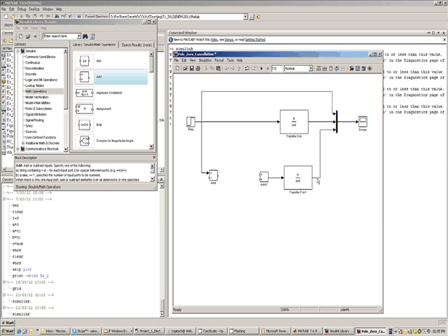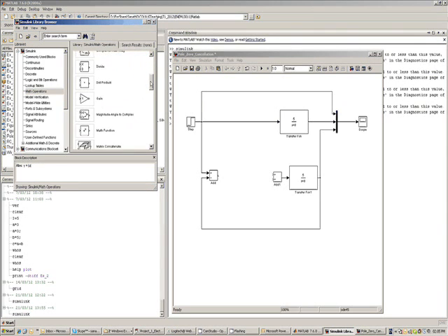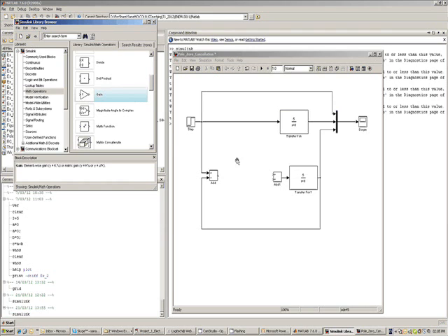Then all I need to do is to introduce the feedback, which goes like this to this summing point, and then now I have to construct the PI controller. How do we do that? From the math operations block, I'll get this gain block, which can be my KP.